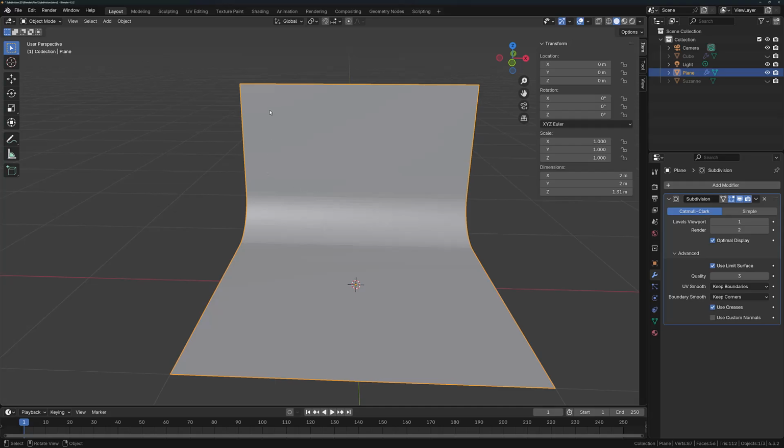This will apply smoothing to your geometry as normal, but it will exclude any edges that are classed as boundary edges. In other words, if an edge has only one face on one side but no face on the other, it's going to be maintained because it's classed as a boundary by the Subdivision Surface Modifier.